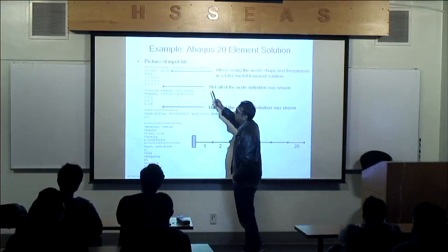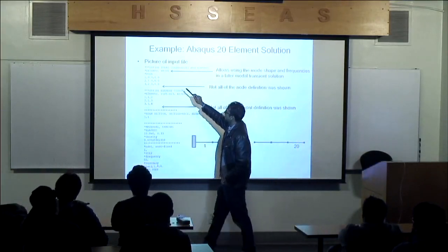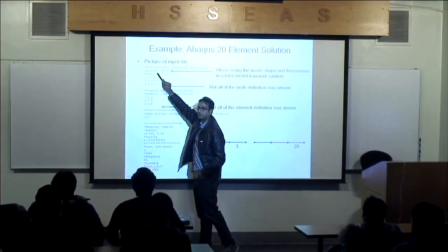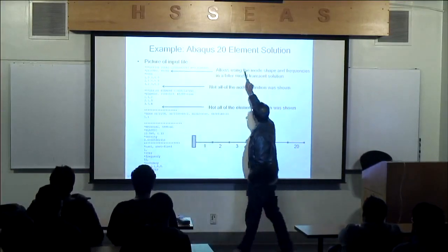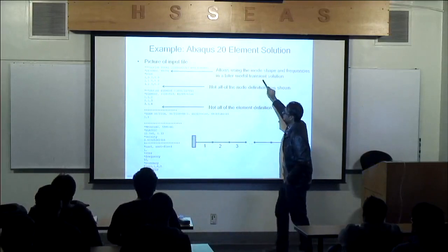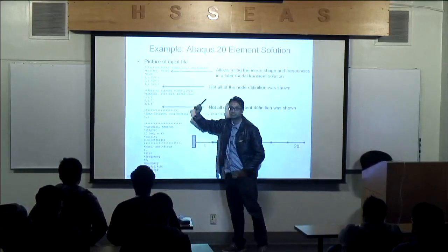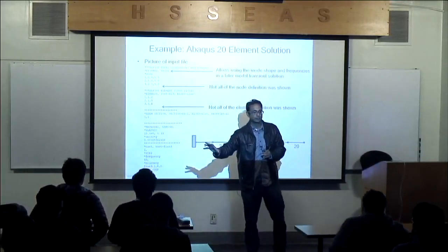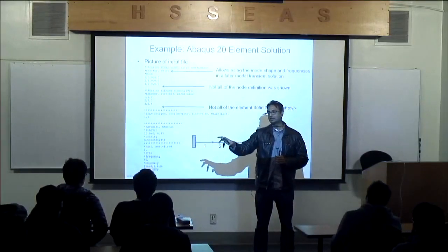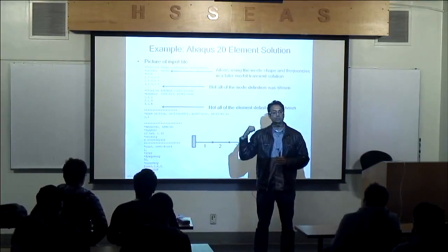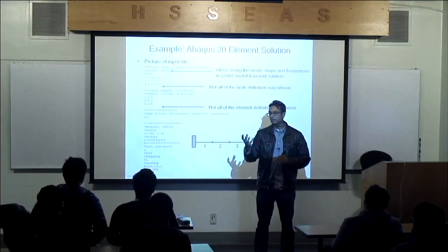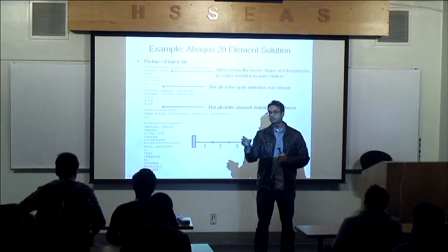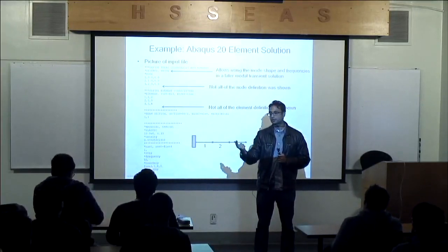All right, so one thing that I added here is called restart, write. I did that because I want to store mode shape and frequency information into this file. It's going to generate a file. It's good to have it. I call that the DNA of this structure. So that file is going to contain all the modes and all the frequencies. You don't have to calculate this again.